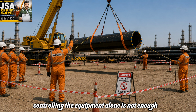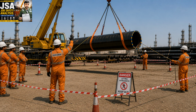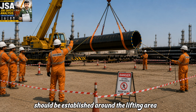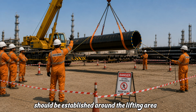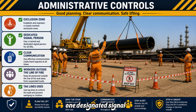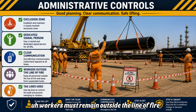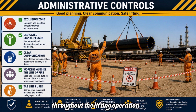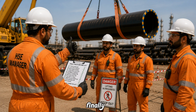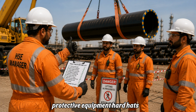Controlling the equipment alone is not enough. We must also protect the people involved. An exclusion zone should be established around the lifting area. Only authorized persons should enter the zone. One designated signal person should communicate with the crane operator, and workers must remain outside the line of fire throughout the lifting operation. Finally, ensure that all personnel wear the required personal protective equipment.